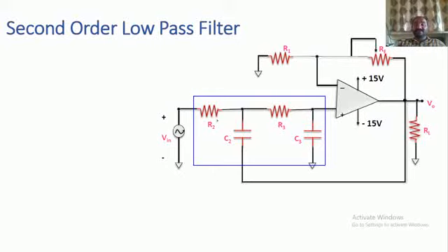The order of the filter is second order, because we are using two resistors with two capacitors. Okay, now the feedback element. Here the feedback element is a pot. Why are we supposed to have the extra resistors?